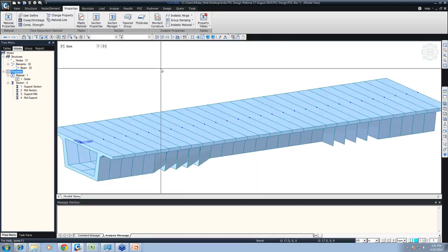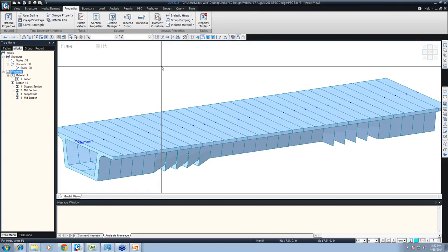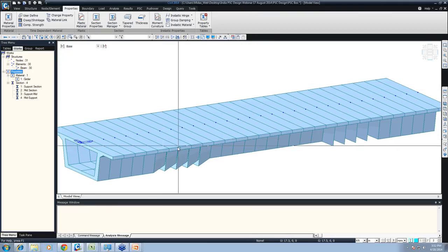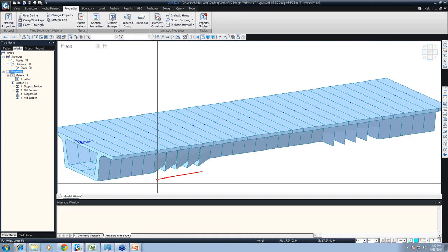Once we go to the solid view, you will find that all the section properties are given, but you are finding some rough adjustments here, right? These adjustments are plausible, because MIDAS will identify each section as a separate section, so each of these sections will have its own I and own J. Whatever ith and jth property tapering we did, it will taper from its own ith section property to its own jth section property. So in that case, we need to generate some tapering properties.